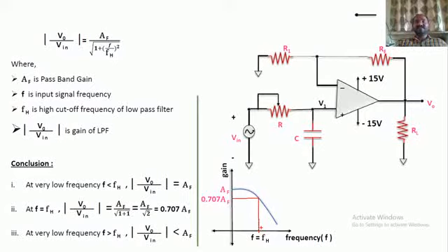So we are choosing the cutoff frequency of the filter practically. Theoretically, fH equals 1 by 2 pi RC. To identify the practical cutoff frequency, draw a perpendicular line from the y-axis onto the curve. From which point? The point at which the AF is reduced by 1 by root 2 times, or where the AF value is 0.707 times.